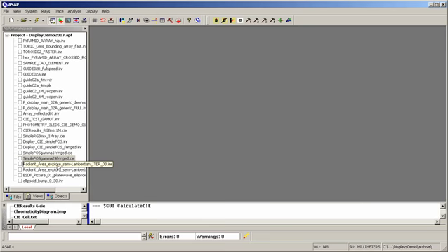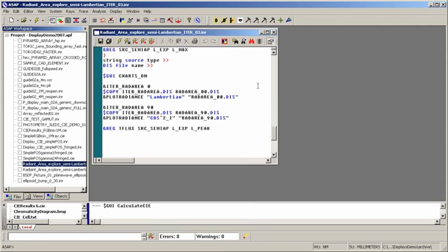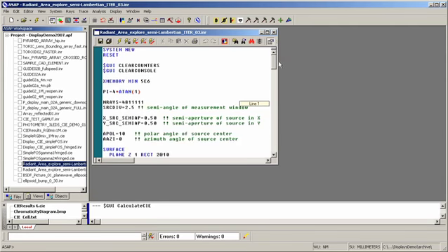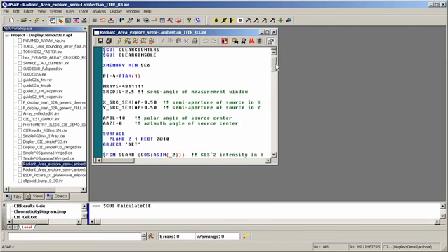Another important issue that we often encounter is the radiance or radiant intensity functions of monitors as a result of viewing angle. We may want to characterize the viewing angle characteristics of a monitor, and what I have done in this example is to simulate a monitor which has a Lambertian radiant intensity characteristic in the horizontal viewing angle direction, and a super Lambertian.